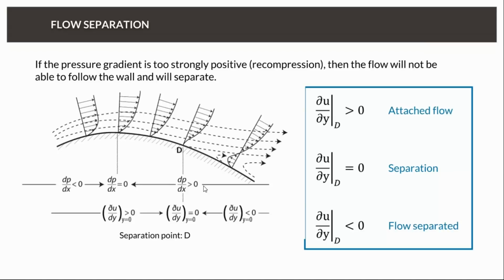This brings us to approach the flow separation. What is happening is you can imagine that the air is flowing above a wall, in this case a curved wall, so due to the curvature of the wall we are creating a pressure gradient. On the flat plate, as there's no disturbance, no variation of curvature, it means the pressure over the flat plate will not change, so the boundary layer sees a kind of constant pressure.